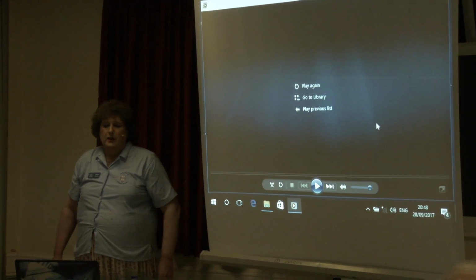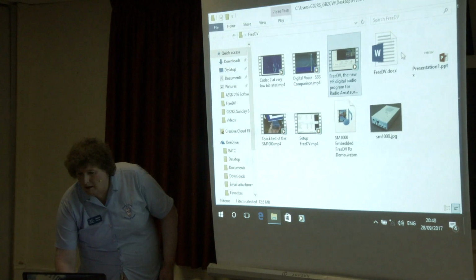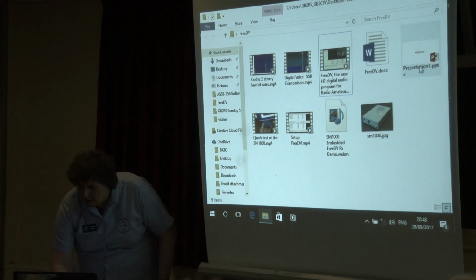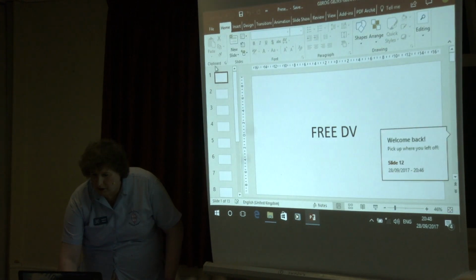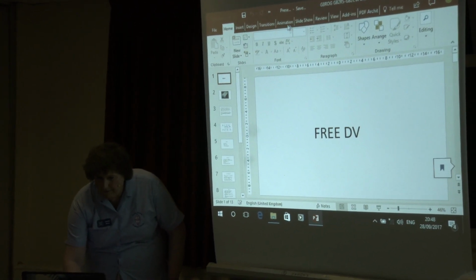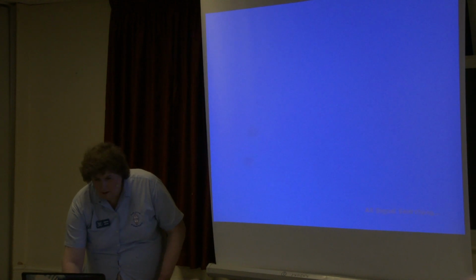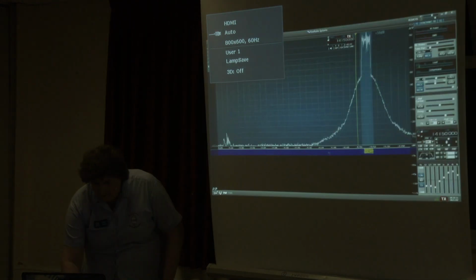So Alison, is it high duty cycle in the same way that, say, a PSK signal would be? Right, I was actually just coming back to that one in just a second. It looked like almost the carrier strength was independent of the audio. Yeah, there's phase shifted carriers basically. There's 75 Hz carriers across the bandwidth. It's 100% duty cycle, yes. Which is a problem. So I could only use it on 25 watts.